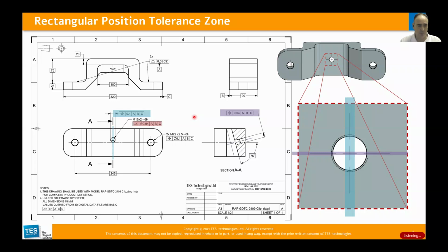So the last specification regarding the axis of the pitch diameter is angularity. Diameter 0.04, and in this case, we can see the tolerance zone as a cylinder. And keep in mind that orientation does not locate, so this cylinder can float within the first two tolerance zones. All in all, a manufactured piece needs to comply with all three specifications.